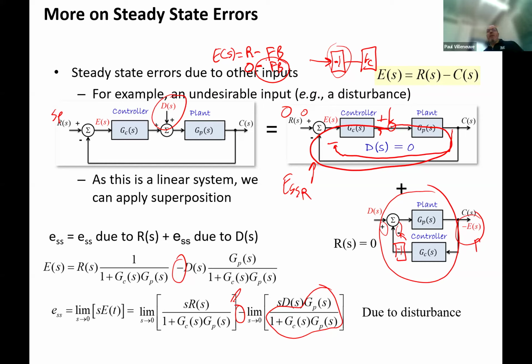So this is where the melding of control system engineering comes in. A lot of it is done with electrical systems, but to actually do real control systems, you have to understand mechanical systems really well, or chemical or thermal systems really well, because these signals are coming in and you've got to be able to translate what that means in terms of what the output value is going to be, or how it affects what's going on. The disturbance normally would be maybe a leak, right? You've got a pipe that's leaking water. That's not what the system is supposed to do. But if there's a constant leak in a pipe, then you would model that as a disturbance. Okay.